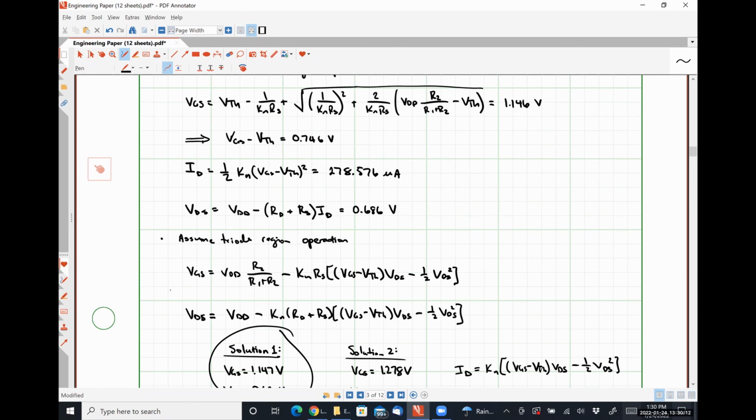When we get into the triode region, that efficiency factor is much, much smaller. Just like we saw for beta in the forward active region versus beta in saturation, we get nice large values in the active region and pretty crappy values in saturation. Same thing happens here.